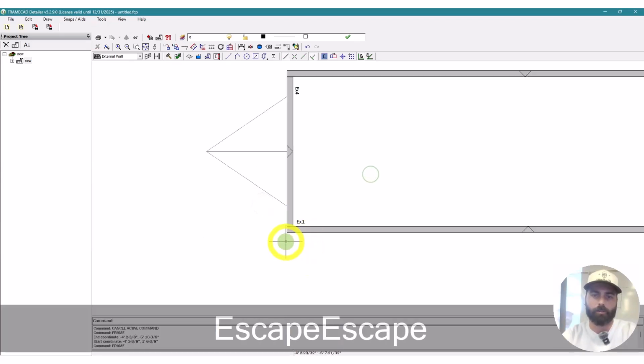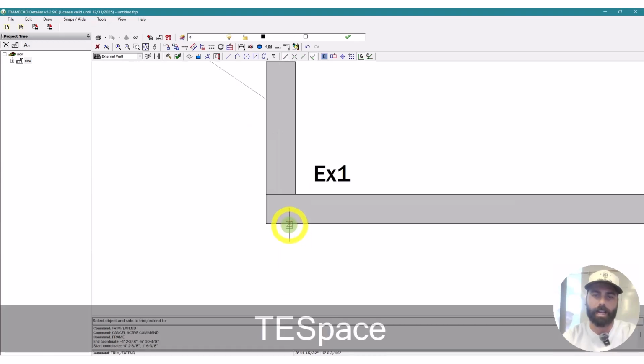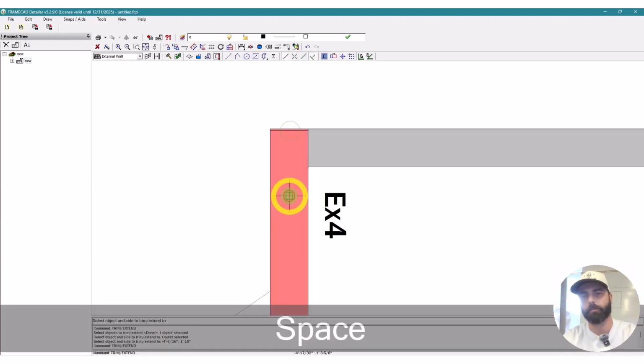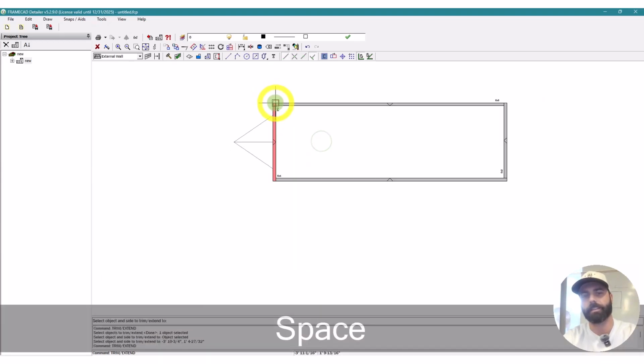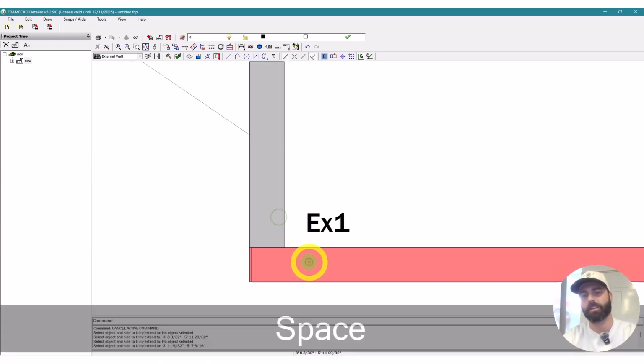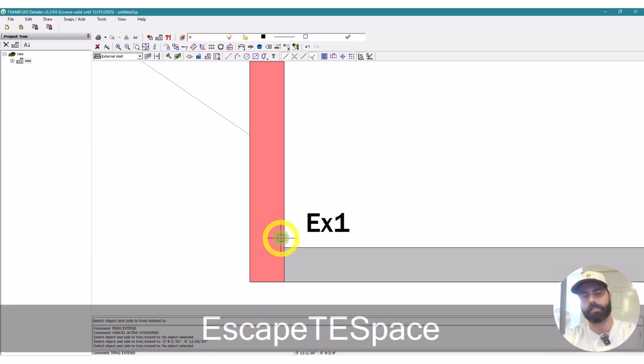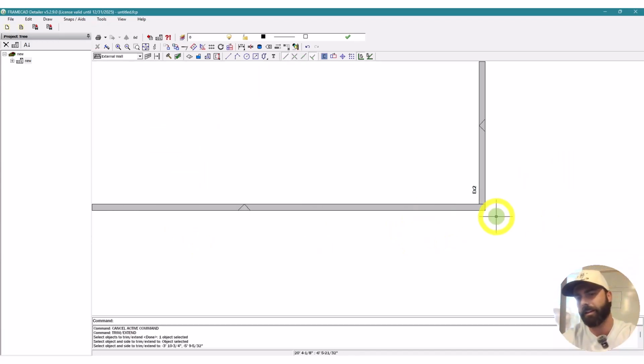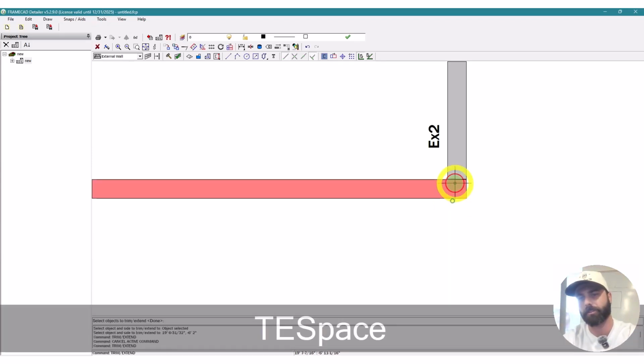So what we'll typically do is have the tongue and rear of the trailer oversail the front from a wind resistance standpoint, holding up that interior wall. We want the front of the trailer, the one that's going to be seeing 70 miles an hour of wind, to be housing that wall that runs the 24-foot length, so you're not relying on the fastener connection to withhold that, you're relying on the entire connection itself. So we'll just bring these back out.